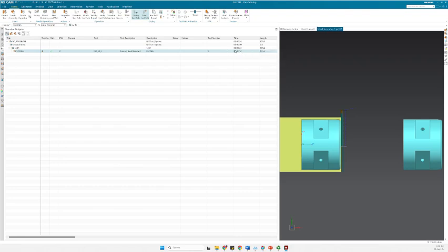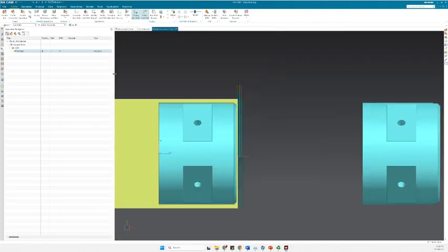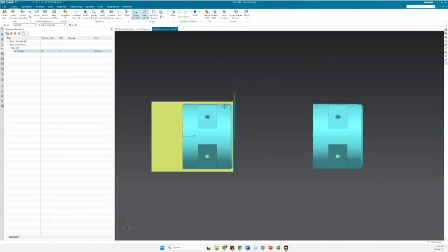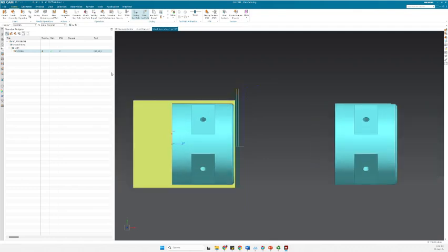This value seems to be too small because I just put a random value for the feed rate and so on. But if you check and put the correct value, you can figure out and calculate how much machining time it takes. All right, but let's suppose that this is fine, and let's go to the next operation, which is the outside diameter roughing.